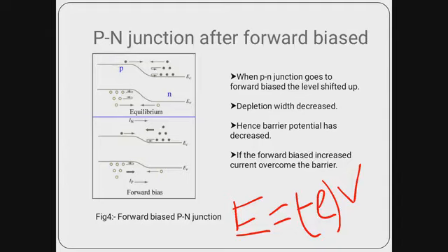But here the barrier has no discontinuity, because we have chosen this is a homo junction. In case of heterostructure, we will see how discontinuity helps and what is discontinuity, how does it form. But here we are not getting any discontinuity, so we are not getting a large amount of current to change small amount of potential externally.